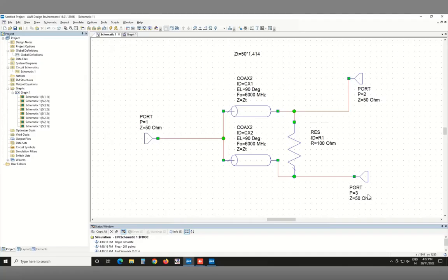The matching condition relies a lot more heavily on the R being 100 ohms for port 2 and port 3. Whereas for port 1, it relied on the transformed impedance of the 50 ohms via the lambda by 4 transformer. Remember that in the even and odd mode case for the matching condition, in one case your transmission line was involved because it appeared as an open, and in the other case, it was not even involved.